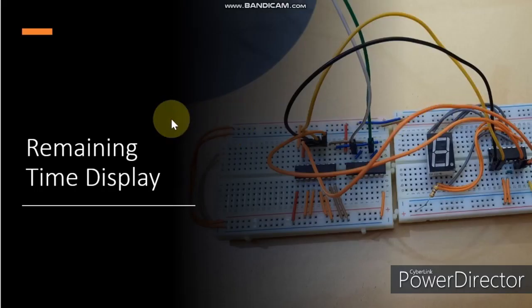Assalamu alaikum. I'm Ishraq, ID 77. We have installed a timer to keep track of how much longer it will take for street 1 to turn green. In our project, this is the High Court Street. To count the signal, we used a 4-bit up-down counter.